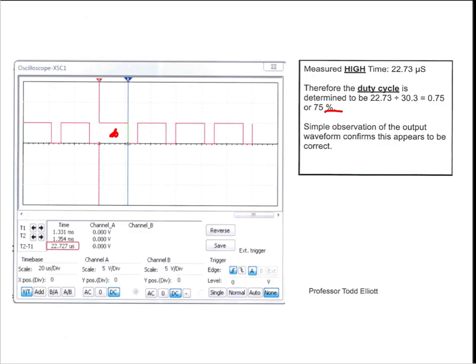Okay, so the 555 is a square wave oscillator. There are slight variances, but roughly the power supply voltages run from +5 to +15. Check the data sheet, but that's ballpark what it is. It gives you a square wave out. And yes, you could use this if you powered it with 5 volts to make a TTL compatible oscillator.